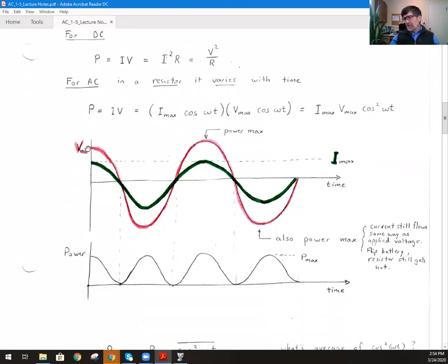It means that here's a graph where V is the red curve and I is the green curve. There's no meaning to the fact that I is smaller than V. They're on different scales. They're different quantities. I've just put them on the same time graph so we can see them. The point is to notice they both reach their peaks at the same time, and they're in phase. So when V is positive, I is positive, and so the power is positive. But interestingly, when I and V are both negative, P is still positive.